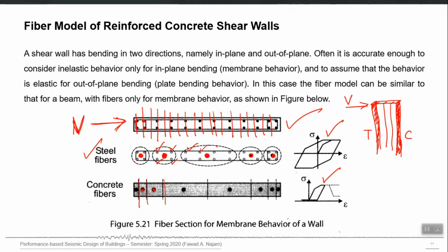Please note that the location of plastic hinges should always be coupled with the actual availability of that ductility in the members also. Once you decide to include a particular plastic hinge in your nonlinear model, you should make sure as a designer that that particular location can develop the ductility which you are depicting in the form of your moment rotation curve, right? Otherwise you are giving a ductile moment rotation curve to your plastic hinge, and your real structure is unable to develop those plastic rotations, and it has a brittle failure.